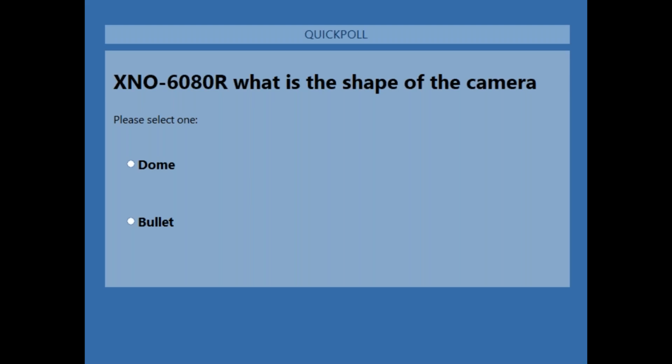Yeah, I unmuted. I have a question regarding this focal length. This mentioned 2.8 to 12 mm. That means it's 2.8 to 12 meter? No, not 2.8 to 12 meter. Mm is just the lens parameter. For example, 2.8 mm to 12. So the lens you can zoom from 2.8 to 12. That's it. It is not meter. You cannot directly relate it to meter. At 12 mm, you can even see 50 meters.